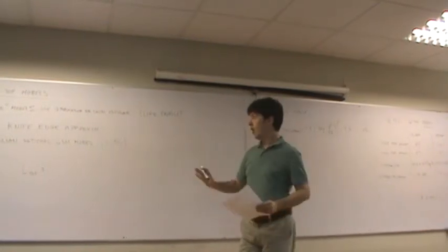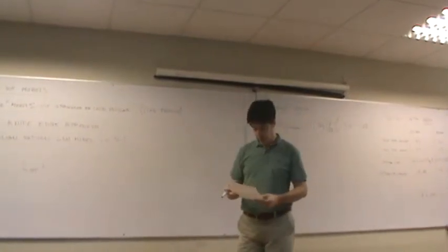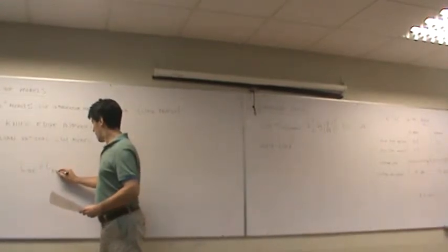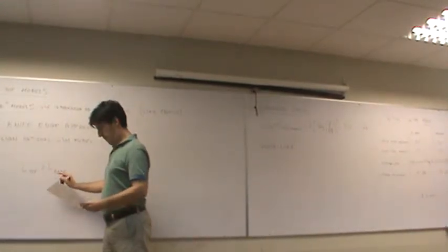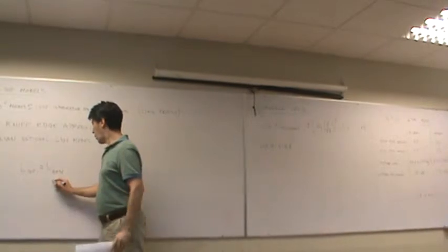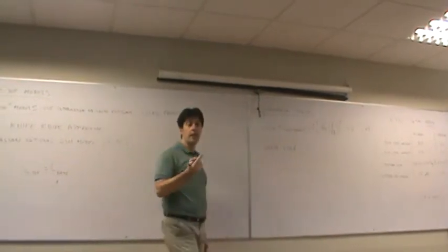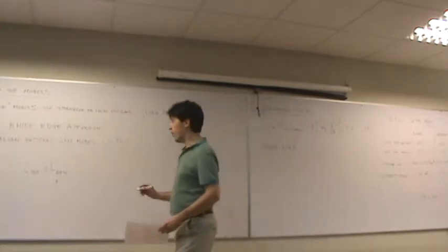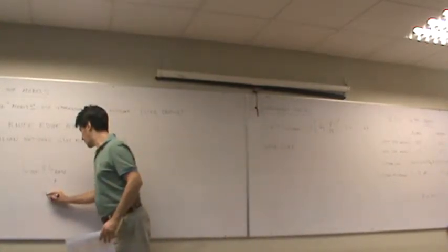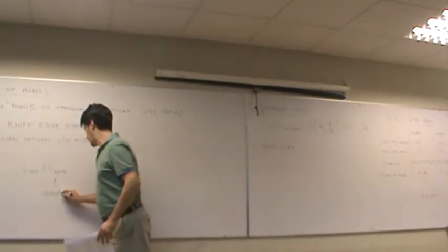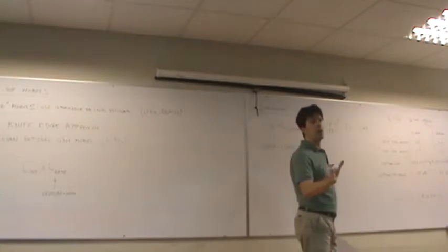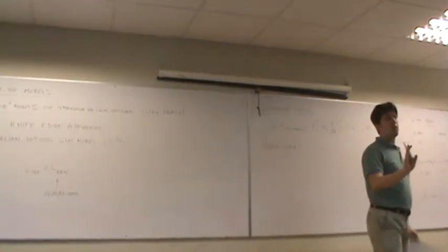It says, we're talking about over-rooftop propagation. We use losses, what we call base losses, that is the losses that you calculate with the Okumura-Hata model. So you take the Okumura-Hata model and you calculate the losses.